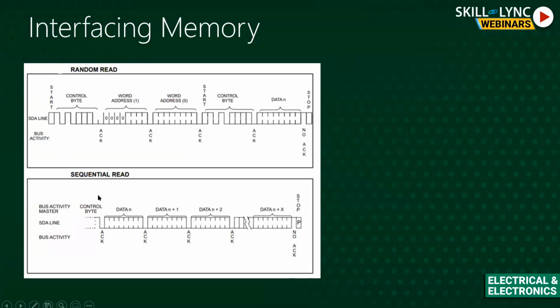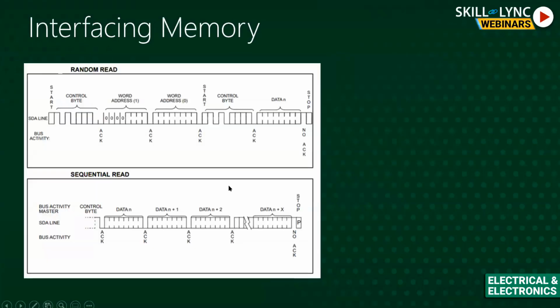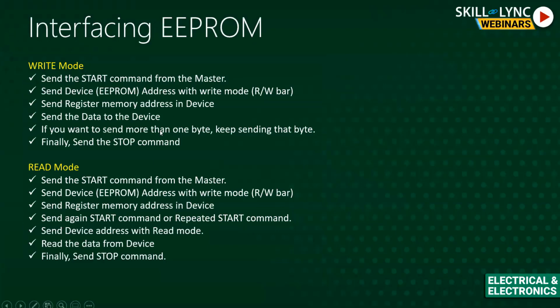Similarly, you can have the sequential read as well, where you will read more than one byte and continue to read those values, and at the end you will send the stop signal. This is the same operation you need to follow. So this is the sequence of operation which you need to follow in case of EEPROM write mode or read mode.